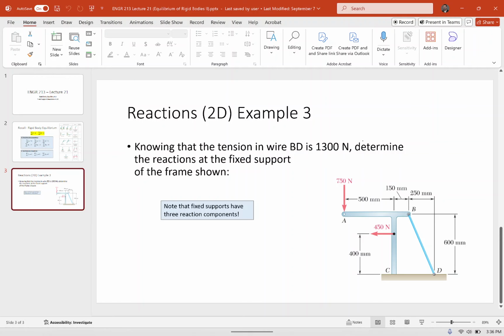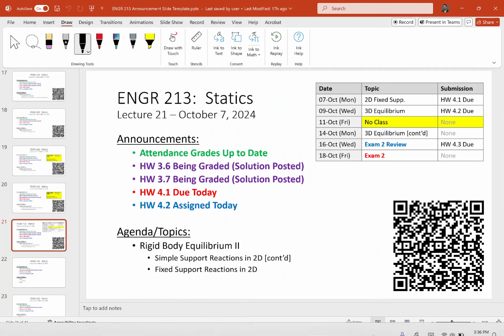And you can't actually solve indeterminate structural analysis problems with only equations of statics. You have to use some other facts, like the relationship between applied loads and resulting displacements, in order to be able to solve the problem. And so you'll learn how to do that in later courses in engineering. But for now, in rigid body mechanics, we have to limit ourselves to systems that are statically determinate. In other words, the number of unknowns match the number of equations of equilibrium that we have.